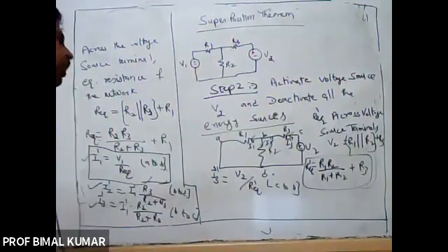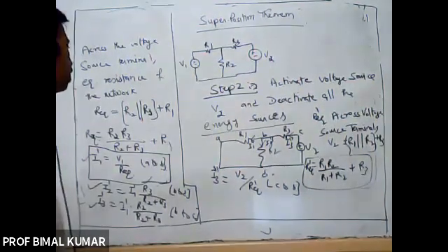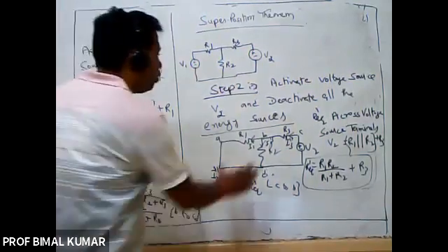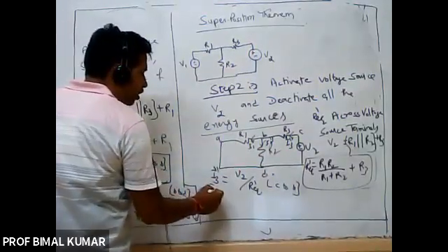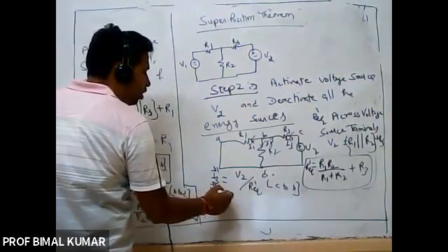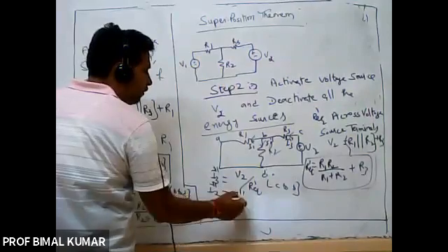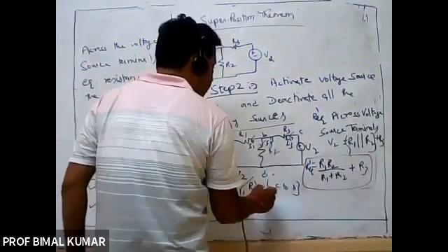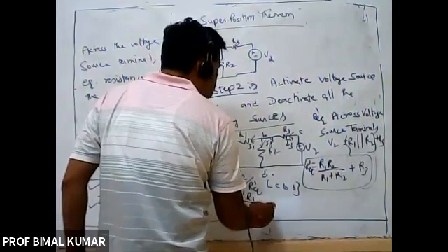V2 is the energy source that will be used for supplying the voltage. So that's why the direction of the current is from C to B, right? Then after that, I2 double dash and I1 double dash may again be calculated by using the current division method. So I2 double dash is equal to I3 double dash into the opposite resistance, that is R1 divided by R1 plus R2.